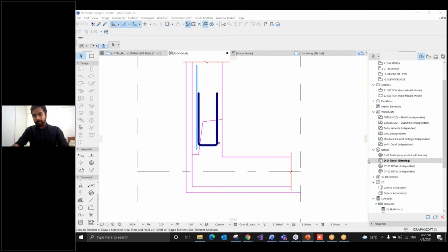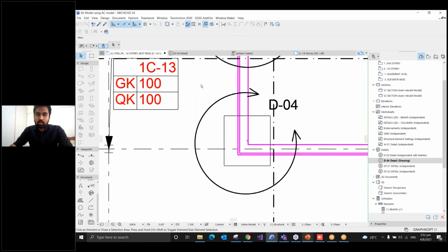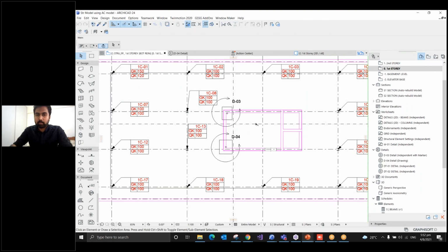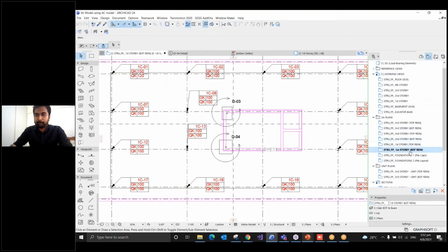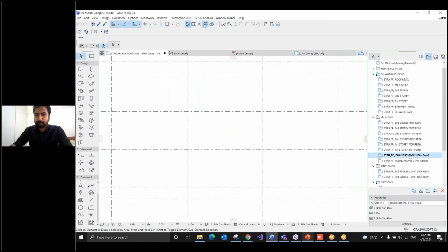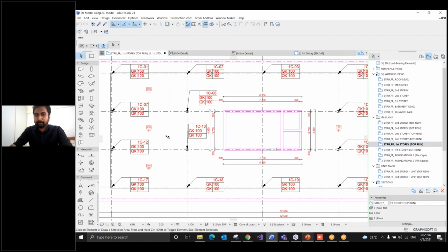How do you model drop slabs? Okay. Drop slabs are normally modeled by adding edges to the side, but we can also use the morph tool to model them. The morph tool allows you to adjust the shape.